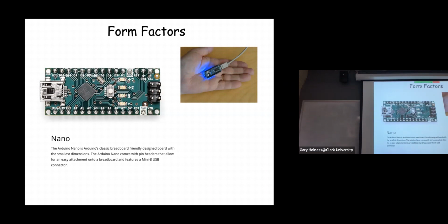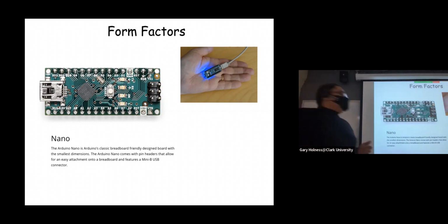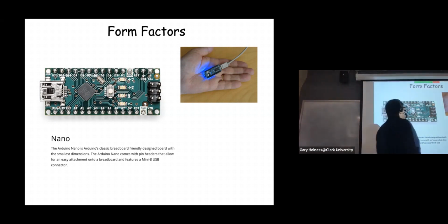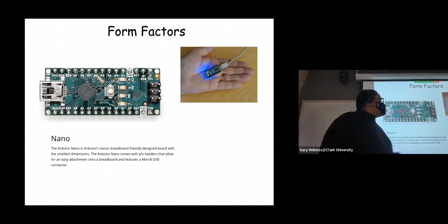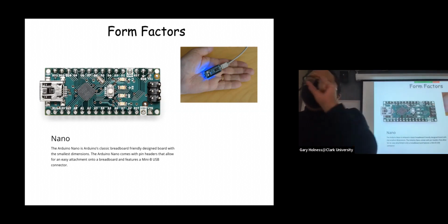If we look here, sometimes you want something much smaller, right, in its form factor. Maybe you're going to put it in a small device and you can't have a huge credit card sized board. This is the Nano. And you'll notice the Nano, this is the underside of the board, it's surface mounted. And you'll see these holes here, these solder beads, that's the drill through, right? The top of the board looks like the following. It has these interface pins, so it's mostly I/O, but the amount of memory and processing on this is very modest. And so it connects with a mini USB connector. And for a sense of size and scale, it's a little bit shorter than a stick of gum, right? It's very, very small. And with these Arduino platforms, you can get one that's button size, really, really tiny.